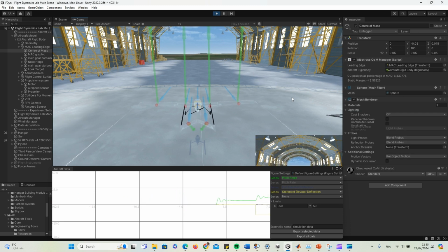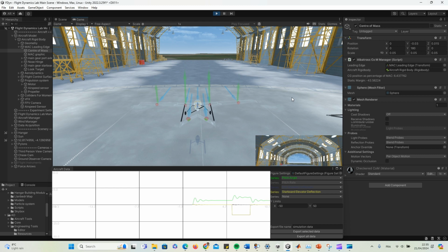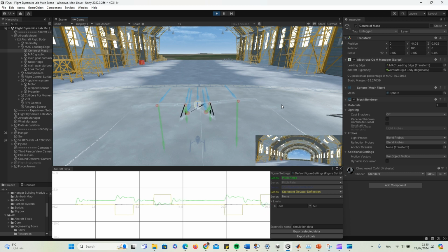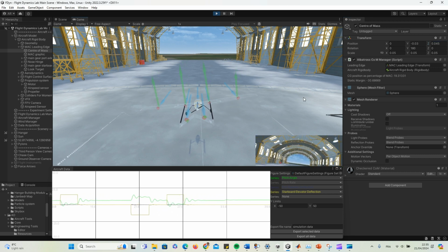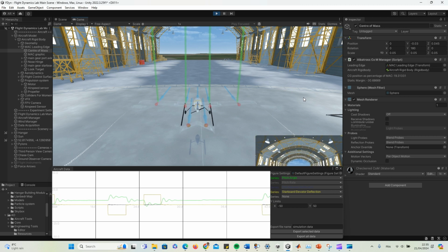Varying the location of the CG will affect how controllable the aircraft is, and as can be seen, putting the CG rather forward on the aircraft makes it very stable. Perhaps this level of stability might make it difficult to control the aircraft in pitch, whereas slowly moving it backwards makes the aircraft a little less stable, but also much more controllable, as can be seen.